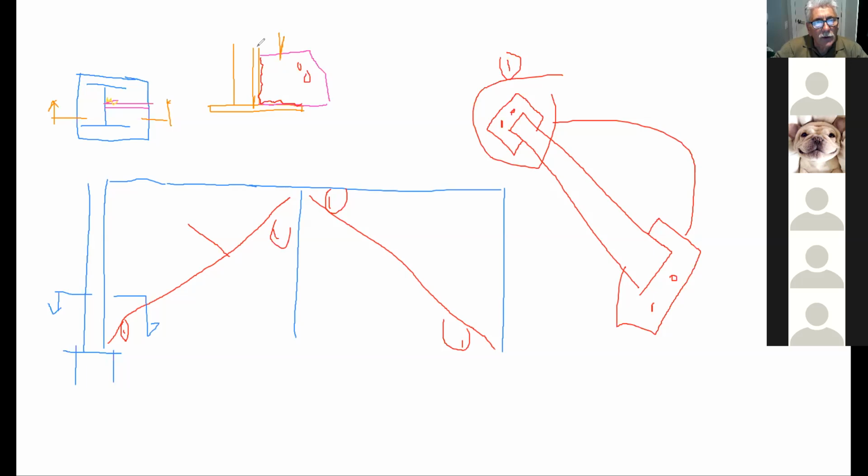Do you follow what I'm doing, Sylvita? Yes, sir. Okay, so that's where you have to look at, on this side here. So I can erase this, Sylvita, everything's good? So do you follow what we're saying, like the gusset plate here? So this gusset plate here will be the same gusset plate here. Fair enough? Now at the top, you have another situation, okay? At the top, it's very similar to the bottom, that instead of having a base plate, you have a cap plate.